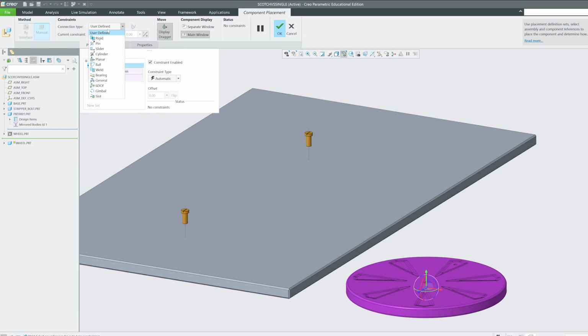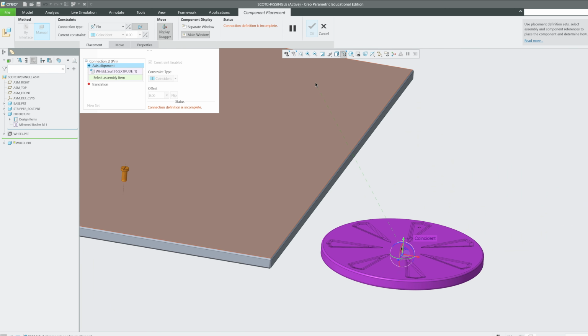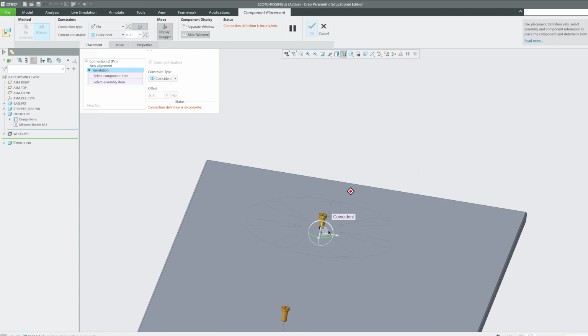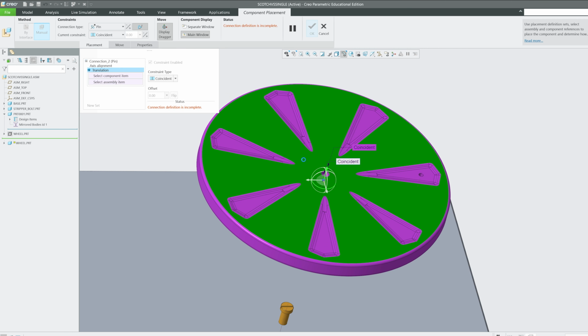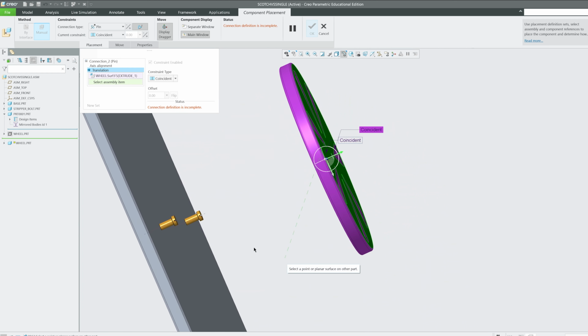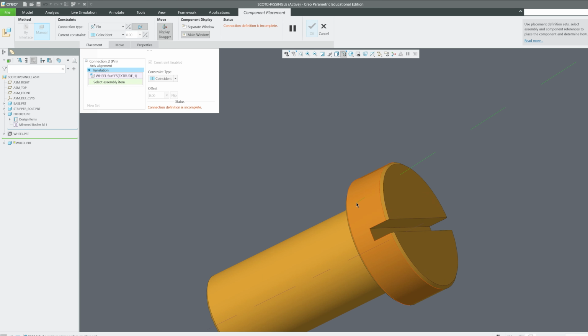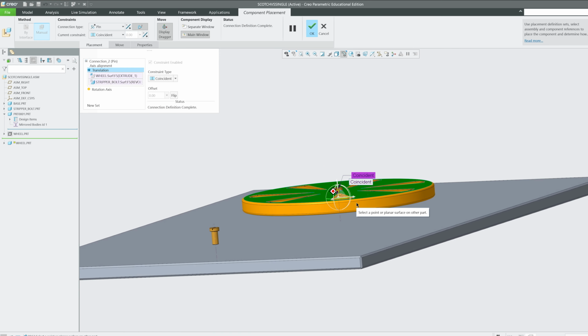So this time what I'm gonna do next here is I am going to pick or create a pin joint, and the constraint here for the pin joint is it requires an axis to axis connection, and then since pin only has 2 degrees of freedom, it can either rotate clockwise or counterclockwise, unlike cylinder joint, which also can go plus z and negative z. So that's not the case in case of pin joint.